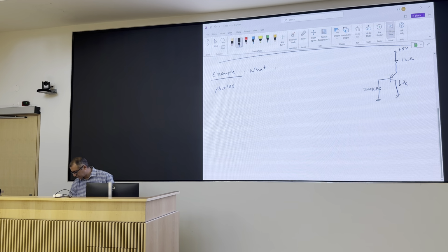You really shouldn't be measuring currents to detect saturation. As electronics engineers, we like to measure voltages. Measurement of currents is a pain. So we like to measure voltages and then see if the device is saturated or not. If the device is in saturation, I have a positive voltage drop across this diode and a positive voltage drop across that diode.